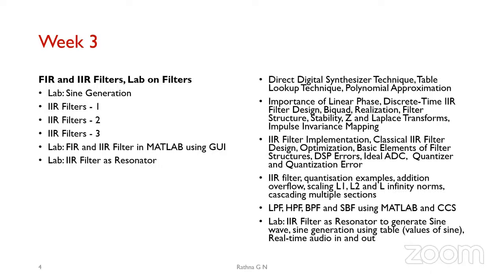The other thing is the errors we mentioned. There are 4 stages of errors. One is ADC quantization, because first we have to convert from the analog domain into the digital domain, so we'll be using ADCs, and there itself we'll have quantization. We saw how sigma delta can give us high rate sampling, so that we can avoid the aliasing filter in the analog domain.